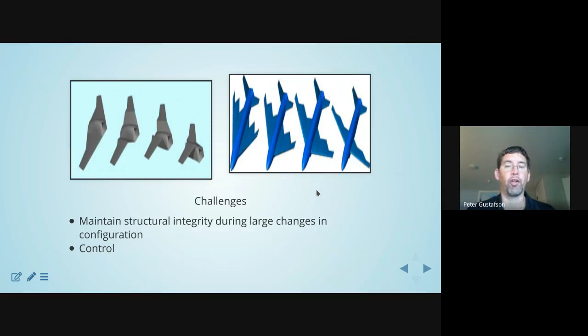Ultimately the goal is to resolve the differences between low speed demands, for takeoff and landing, where you want a large wing area, very high aspect ratio, and very little sweep, with high speed demands, where you want a relatively small wing, a high degree of sweep, and a comparatively low aspect ratio. There are a number of developments going on in the aerospace world right now with regard to wing morphing. It's a modern challenge, really an exciting design opportunity if you happen to get into that area professionally.